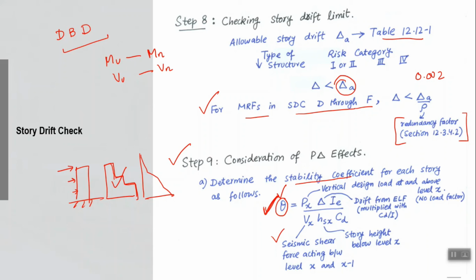So there are two basic methods: large displacement analysis and P delta analysis. Large displacement analysis is a more comprehensive analysis. P delta is its shortcut, its subset, right? So P delta can account for geometric nonlinearity using some approximate formulation, right? But it is accurate enough for our civil engineering structures. It is almost as accurate as the large displacement analysis, right?